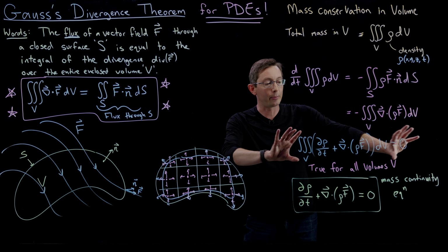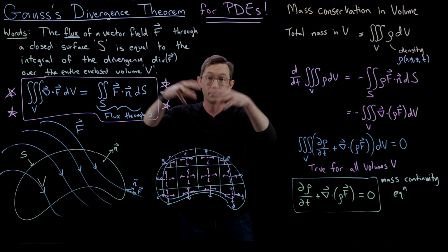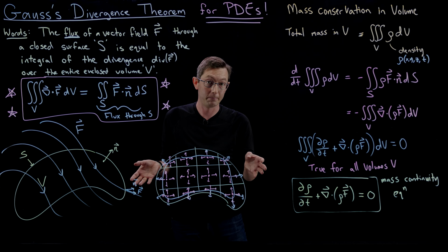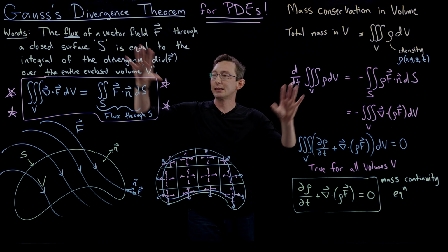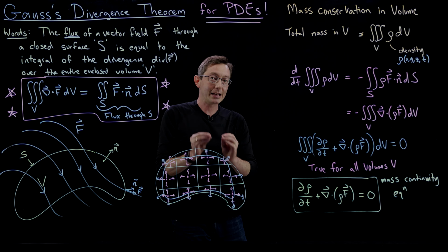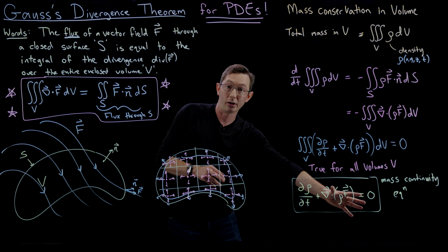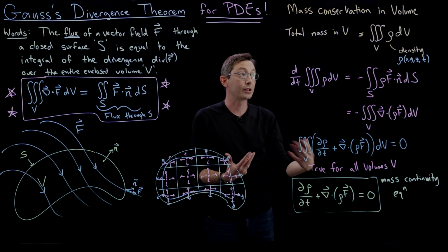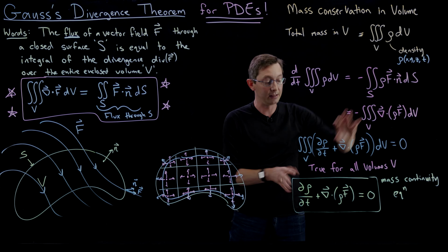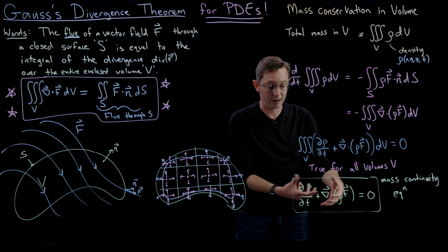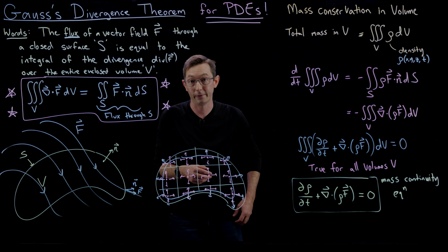And I can only represent the integral effect in a control volume that's large enough to include that discontinuity. Okay? So what I'm going to do is take a step back and summarize. And I think in the next video, I'm probably going to dig a little bit deeper into this mass conservation equation and show you what happens, for example, if I have an incompressible flow. If my density is a constant, then we can derive specific quantities that have to be true for this fluid flow F.